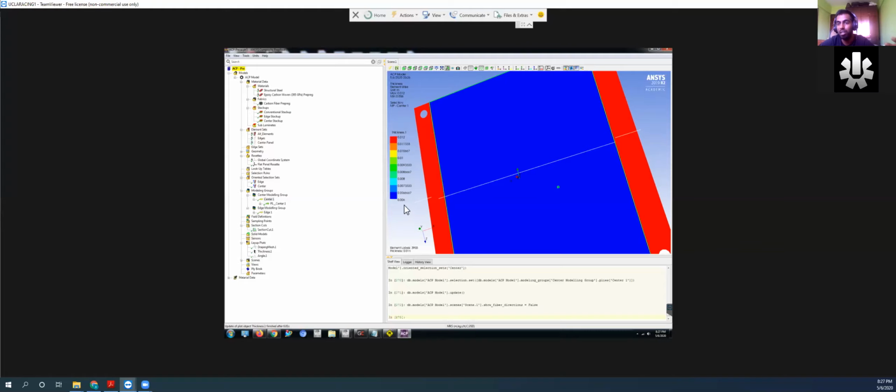And then same thing goes for the center. But in this case, we didn't do even symmetry. We just said no symmetry. So ANSYS did not mirror it along the center axis. So you just get what you put is what you get. So in this case, we got 3 plies times 2 millimeters, 6 millimeters. There's blue. You can see the center is blue. So pretty much what we expected to see.